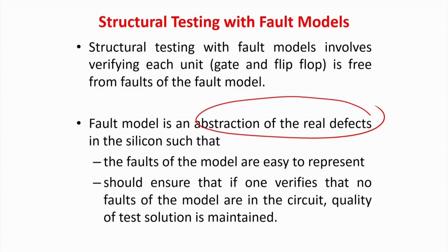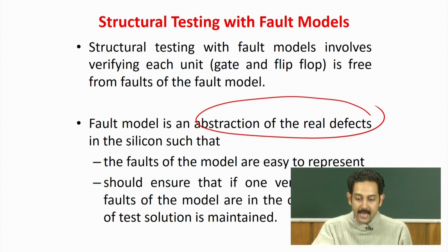That is, if you go for transistor level testing, or physical means, layout or such kind of testing of the devices at the fabrication level, like testing of the vias, testing of the interconnects, that may blow up all the algorithms and the time required to do the testing, and it is also not required. It has been found that if you have really good quality fault models, then the second point should hold: if one verifies that there are no faults of the model in the circuit, then the quality of test solutions is maintained.